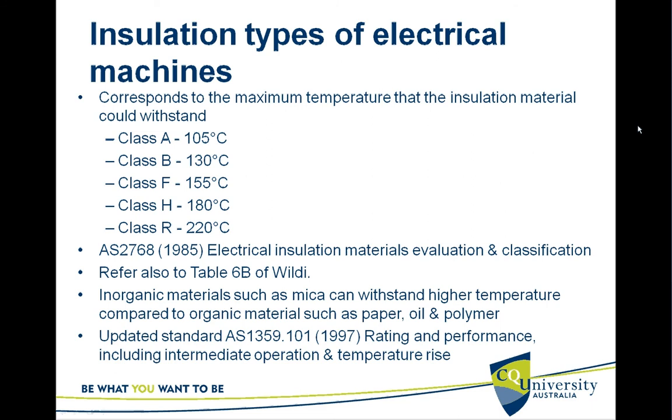Class A insulation could withstand up to 105 degrees centigrade, class B 130, class F 155 degrees Celsius, class H 180 centigrade, class R 220 Celsius.